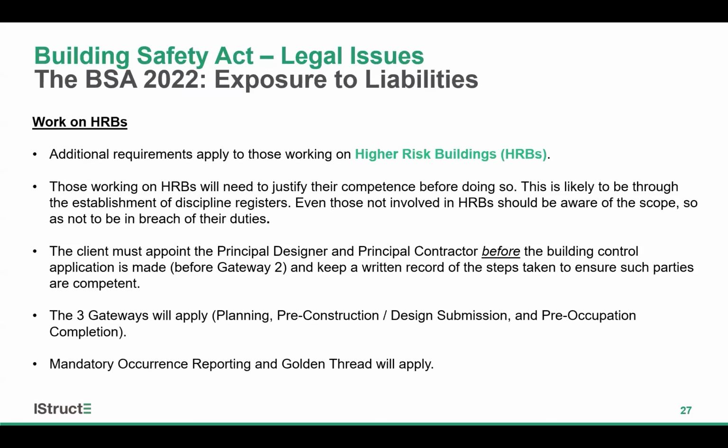So before then, I just want to explore the additional exposure on high-risk buildings. Parties working on high-risk buildings need to justify their professional competence to work on them. And this is likely to be through the establishment of discipline-type registers, which I'll discuss in more detail later. But even those not involved in high-risk buildings should be aware of the scope so as not to be in breach of their duties. The principal designer and the principal contractor need to be specifically appointed by the client before Gateway 2. And again, I know I'm repeating myself, you should always take steps to make sure you are clear on the role and that it is properly defined in your appointment and scope of works.